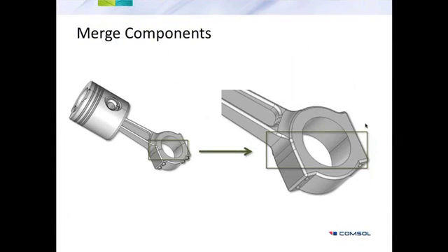So, for example, in COMSOL you have tools to merge objects together. By merging those together, you have a much simpler interface with far fewer spaces that you need to resolve with the meshing. Then you would have the same material properties throughout the component itself.